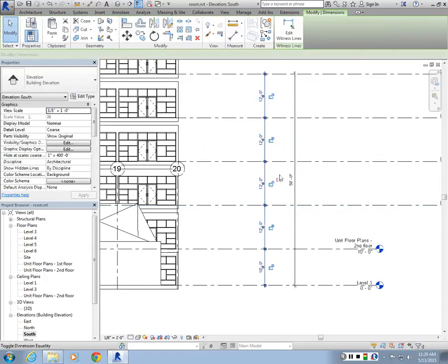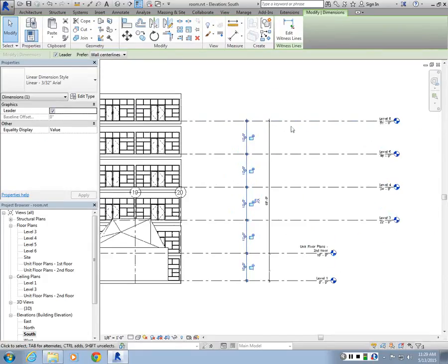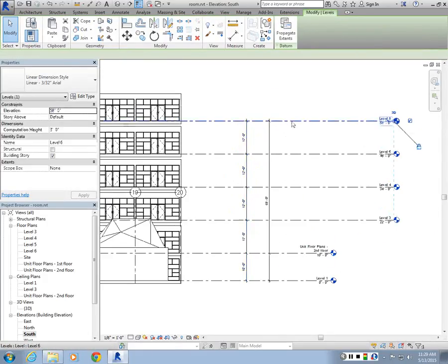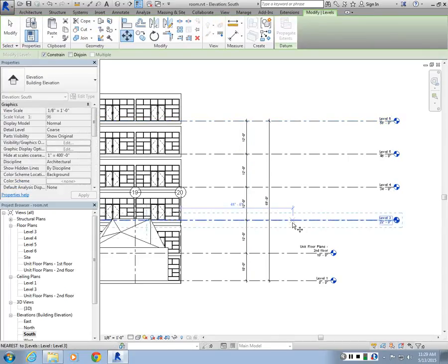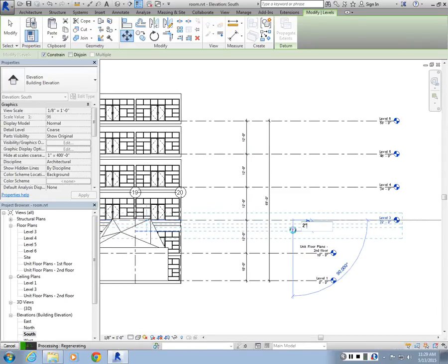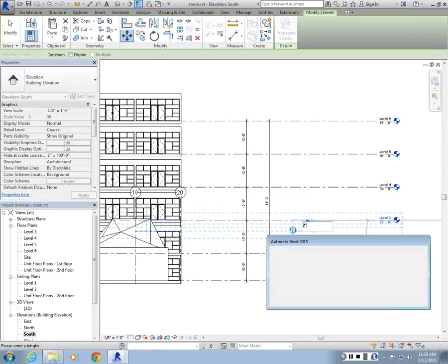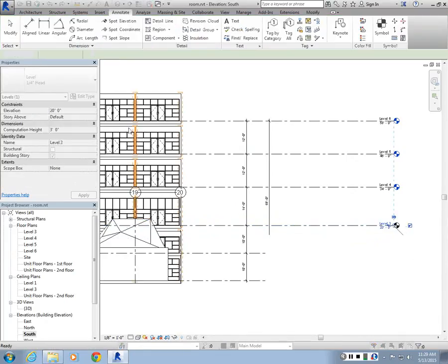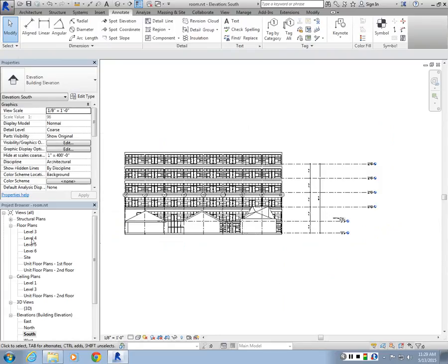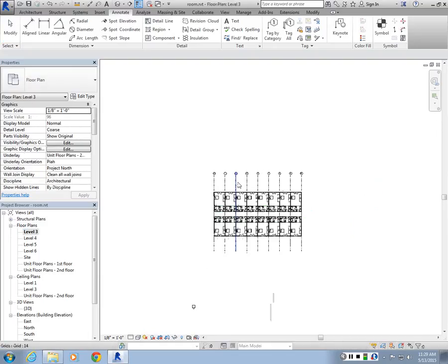I mean, if I hit equalize, it won't work, so we want to set this level to be in the correct height. But I guess I can go about adjusting these levels as well. It's gonna take some time, and it's giving me already some errors. So let me go back and maybe delete some of these levels and then do the vertical copy again.